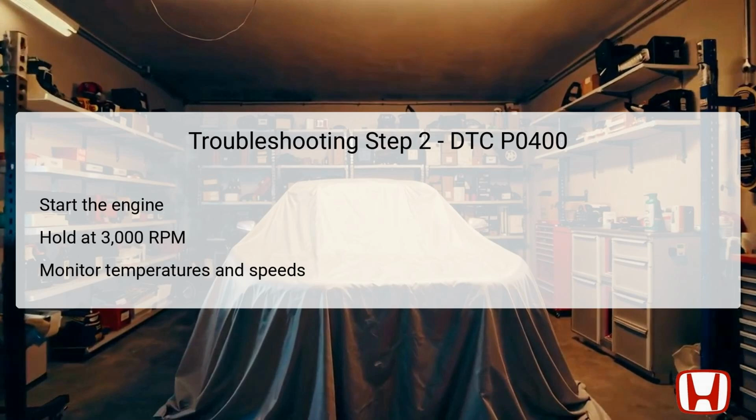Additionally, check to see if the transmission is in drive, D, and conduct a test drive, maintaining a speed below 25 miles per hour for at least 5 minutes. Following this period, increase the vehicle speed to 26 miles per hour and maintain an engine speed between 1,400 to 3,000 RPM for over 10 seconds with cruise control engaged. All these variables contribute to establishing whether the EGR system functions properly under various conditions.